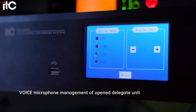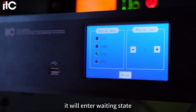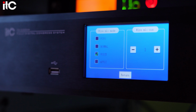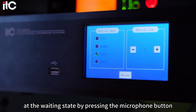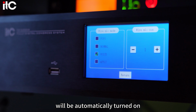For voice control mode of open delegate unit, waiting mechanism. When the number of opened microphones reaches n, here the wired microphone number, it will enter waiting state when turning on a new delegate unit, and the maximum number of waiting units is also n. The delegate unit can exit the waiting state by pressing the microphone button. When a certain open microphone is turned off, the first microphone in waiting state will be automatically turned on.